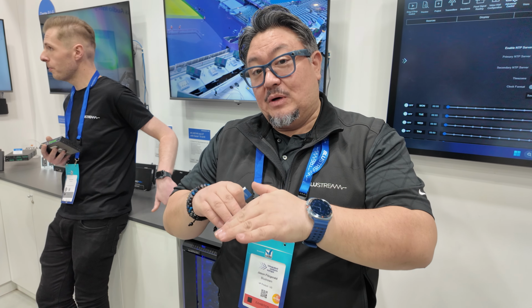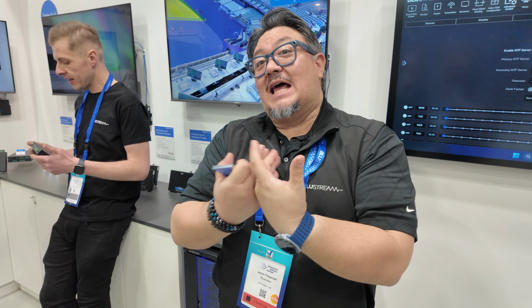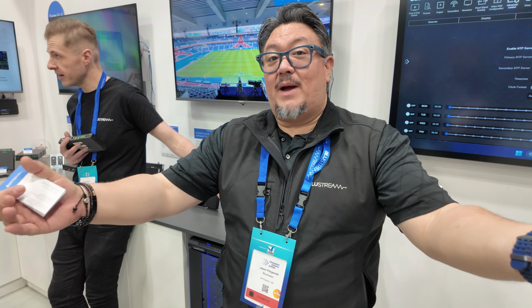The IP350 takes that same platform and adds Dante capability. So now we have Dante and AES67, of course, in the IP350 platform, for all sorts of scenarios. So I can take audio from an HDMI input and demux that audio, or strip it off, and send it directly into Dante. They also have analog balanced in and out, so I can take an analog input and put it into my transmitter, put that into Dante, or at the same time I can take Dante and take it out of the IP300.